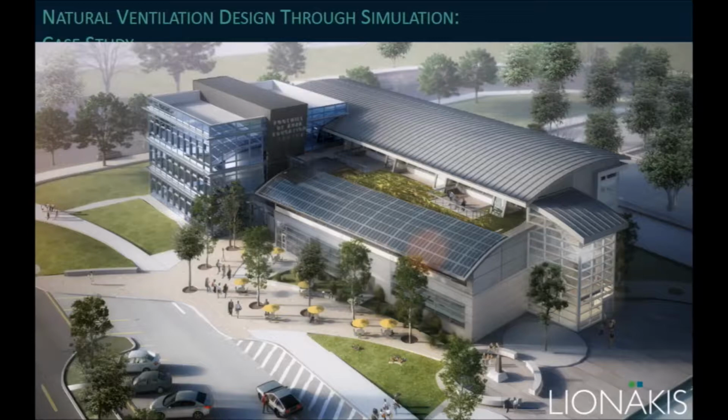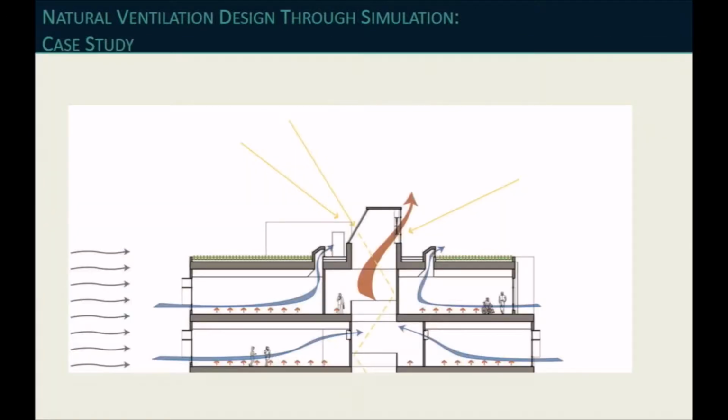So here's a rendering of the building. It's a classroom building. Generally, on the lower parts down here, the classroom buildings are facing south and facing north on the other side. So the concept for this building was to utilize automated louvers at the perimeter, with a relief path into the atrium, and then relief out of the top of the atrium, so you're combining wind-driven effects with stack effects. And the project also utilized radiant slabs, so we had both heating and cooling embedded in the slab.